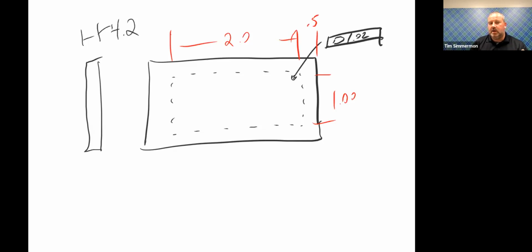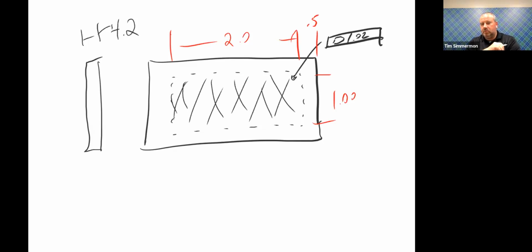So without that box created, and you'll see that in a handful of different ways, some people might cross-hatch that box and say within this area. Without that box or some other defining feature, you will assume that it means for the entire face. Okay. Perfect.